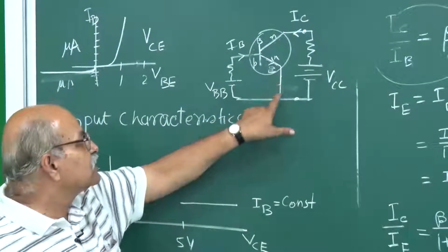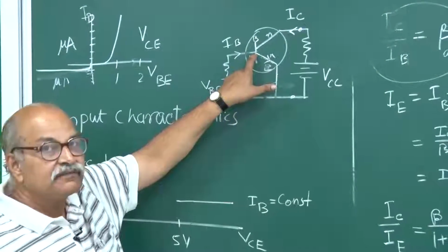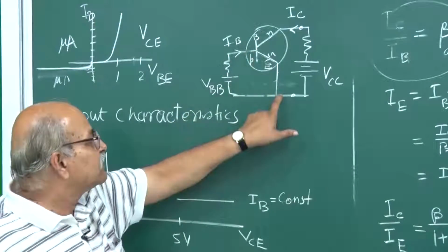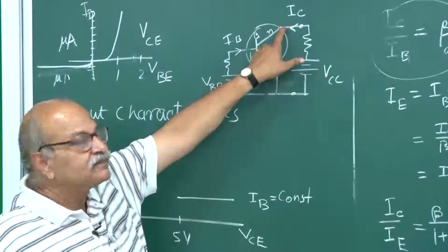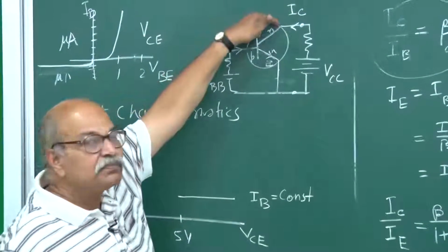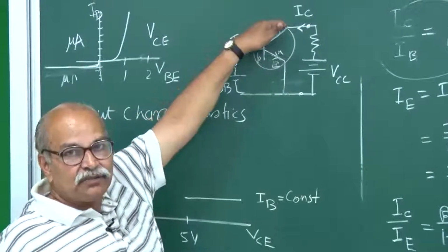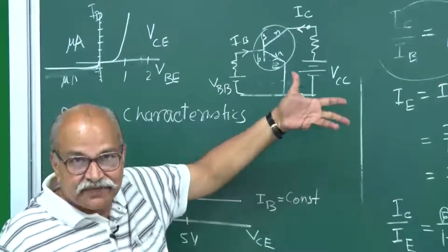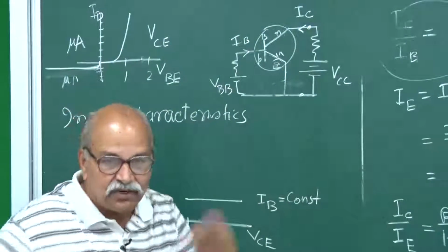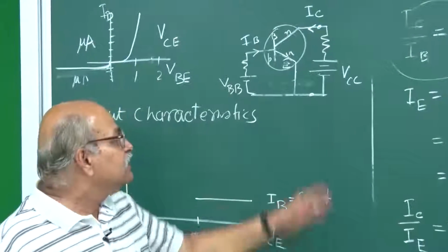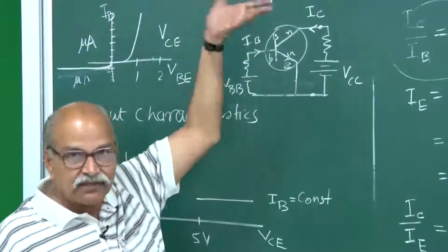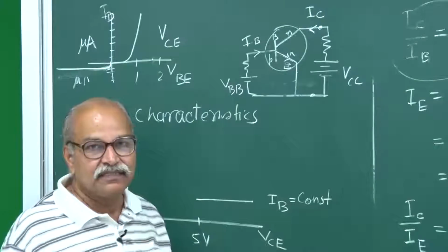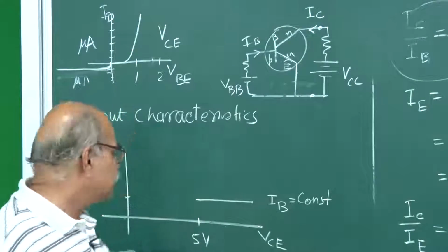So with respect to the base, this is also positive. And so you don't have reverse bias, you in fact have forward bias, and it will not draw electrons from there, and these are lightly doped, so they themselves are not going to give significant current. So the current will be almost 0 here.